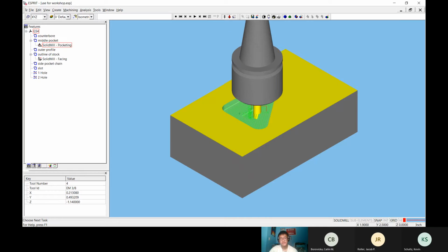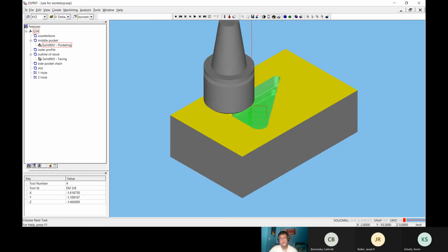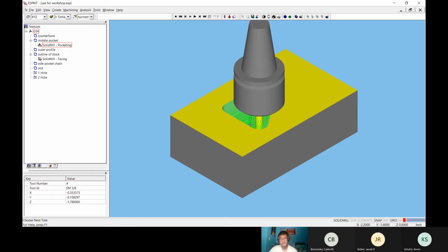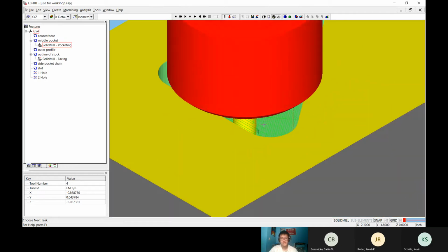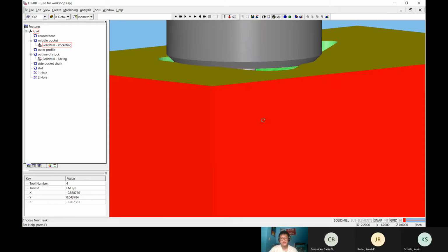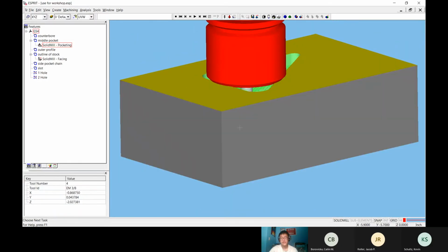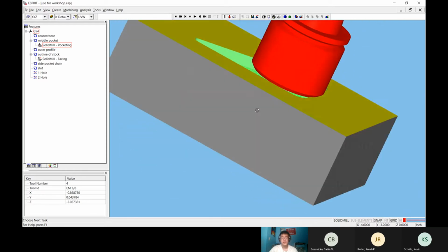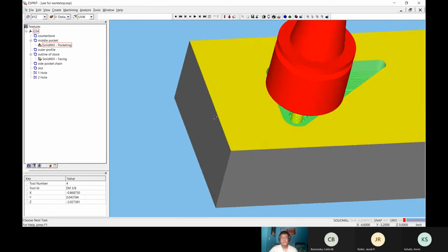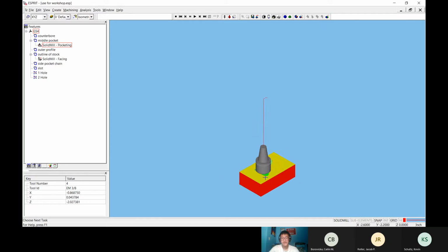And then it's doing a little cutting. You'll soon realize that there is a problem. Just wait a second. Boom. Okay. So what happened is that the tool holder has hit the part, and when there's any sort of crash, it's just gonna blink red. The easy way to fix this is just put in a longer end mill.